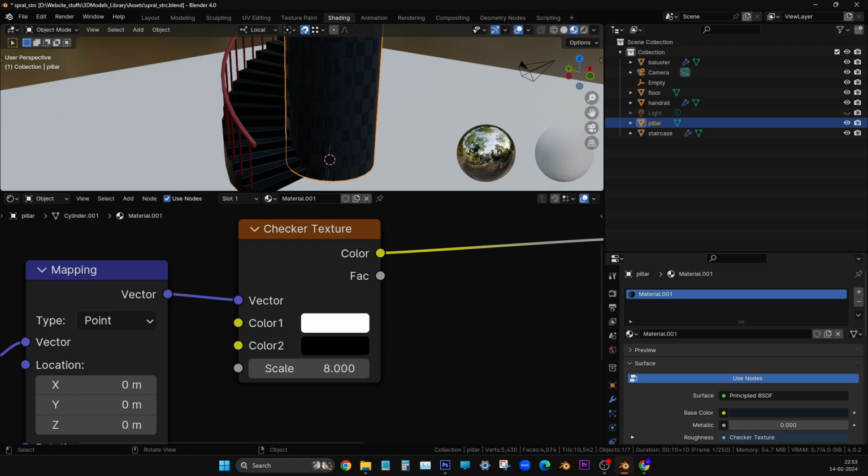I think you have to increase even more, so maybe 2000, and diffuse to 300. I told you, in Blender they keep it very low by default. We have to increase it.